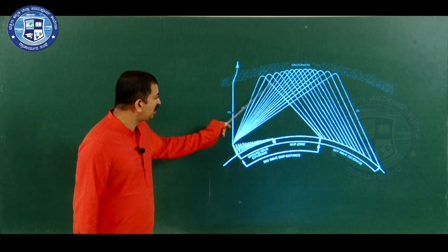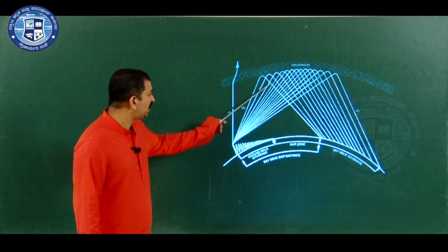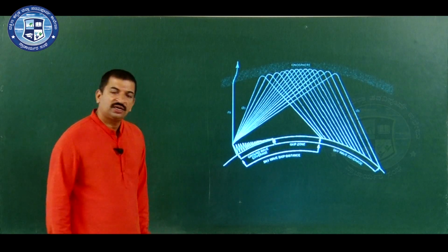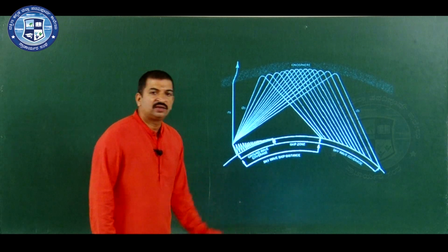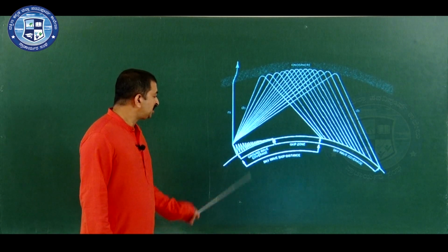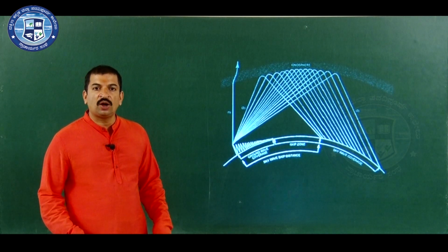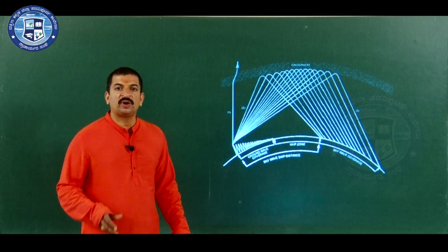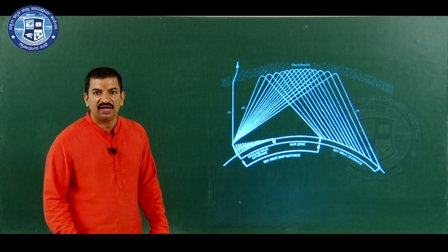Let me consider a ray which is incident on the ionospheric layer with an angle equal to the critical angle. So, this ray returns down to earth with shortest distance from the transmitter. Now, let me consider the point where the first skywave is received. Now, consider the ground wave. The ground wave propagates along the surface of the earth. The ground waves can propagate certain distance and afterwards it dies out. It loses energy completely and dies out.